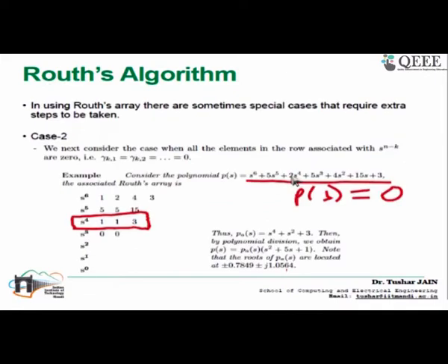So here what we are testing is basically the absolute stability. Once we talk about marginal stability, sorry, relative stability, then we introduce the difference, which is why I introduced the term absolute stability: here the polynomial is given to us and I'm just checking whether this polynomial is Hurwitz or not. And what does it say? There are some roots of this polynomial. Once you solve this equation, there would be some roots. Now you know the exact location of the roots in the S plane, and based on that you say whether the system is stable or not.